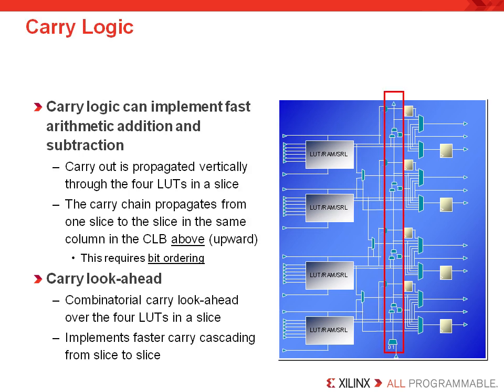Carry logic is the dedicated hardware resource that improves the speed of arithmetic functions, such as adders, accumulators, subtractors, and comparators. From the diagram, you can see that the left-hand slices are grouped into one carry chain. Please note that carry logic propagates the carry signal vertically upward.